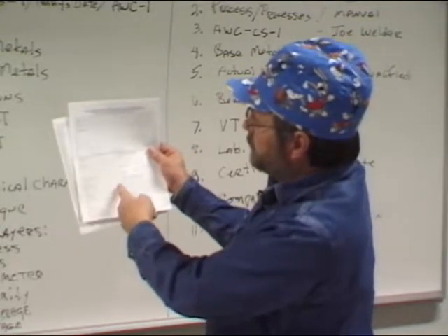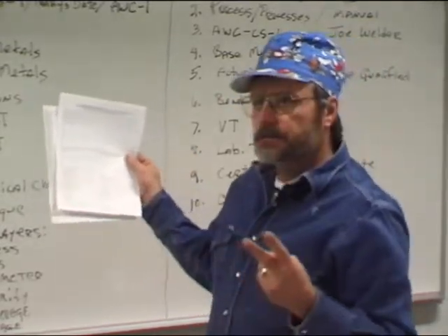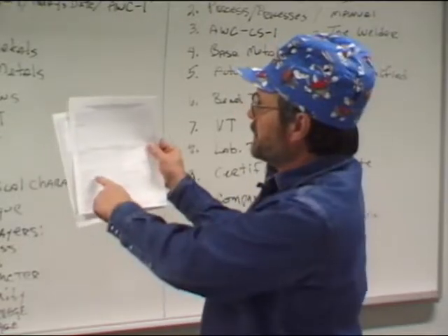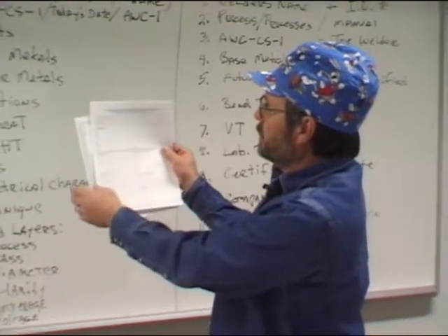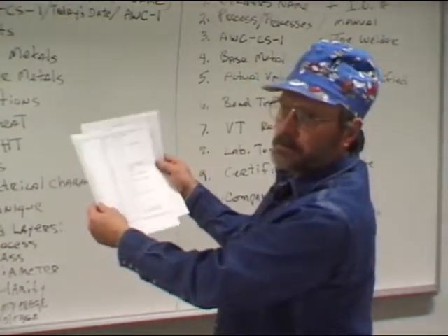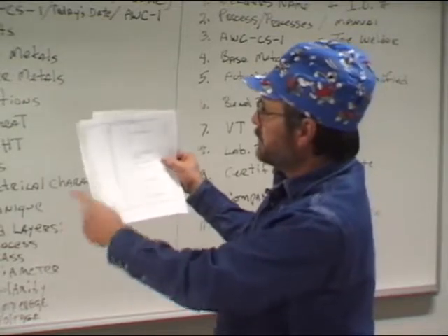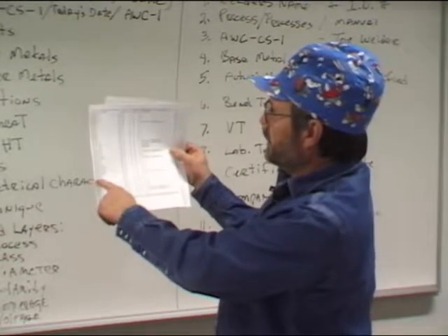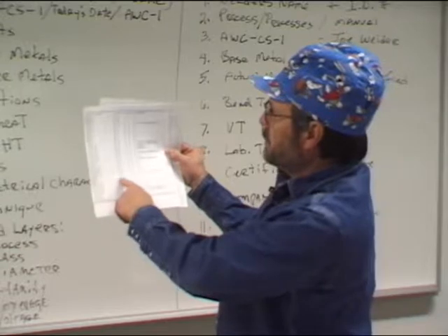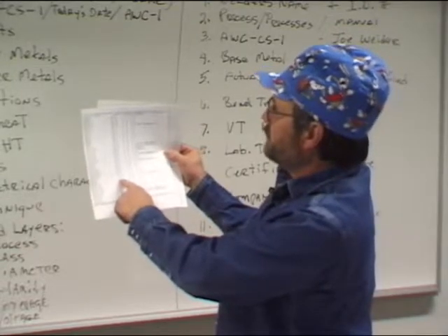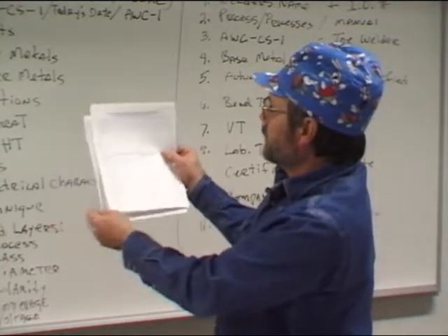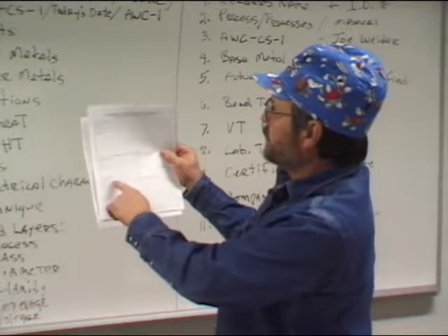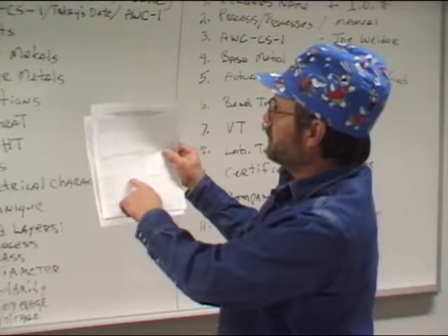Now you notice it's got 2 columns. And since we're using 2 different types of filler metal, you'll write SFA number 5.1 here. And then the other welding electrode we're going to use is 7018. So you come down here and you'll find E7018, and you'll see that it is also a 5.1. So we're going to write 5.1 over here. So we have 5.1 and 5.1.